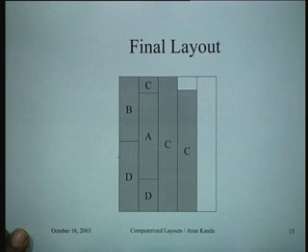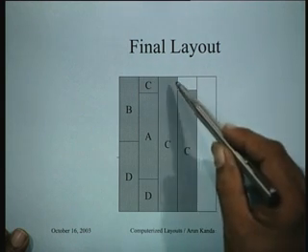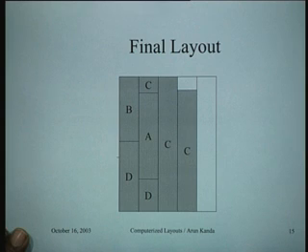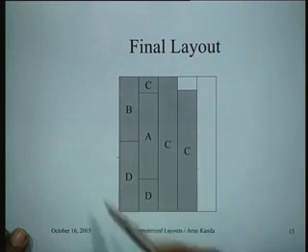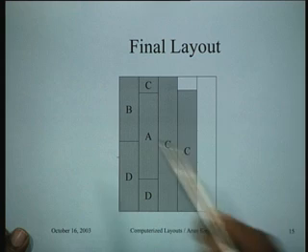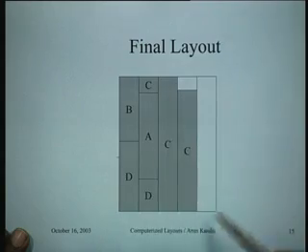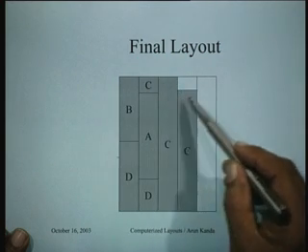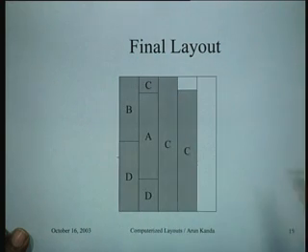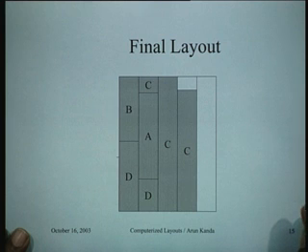And another thing which happens is that the final boundary need not necessarily be rectangular. It could be rectangular if the total area of the departments is equal to the total space that you have available. So if you make a provision that you want to locate the departments in exactly a certain space, and you make sure the total area is the same, and that area you divide into strips, then of course this would happen. But if you just lay out something in the area, then the final boundary that you get is also very peculiar, right?